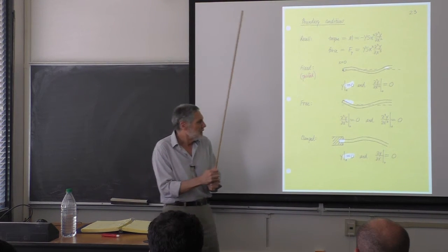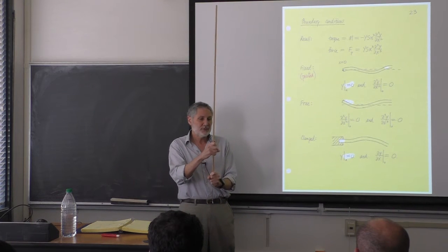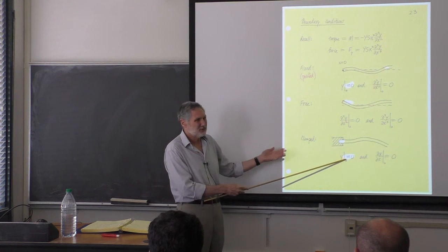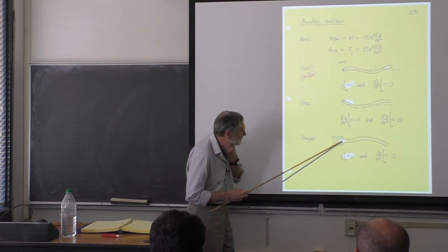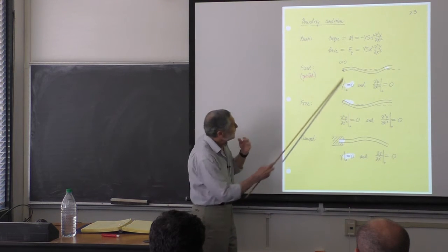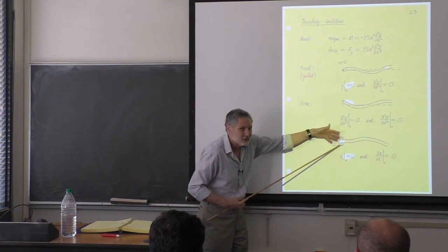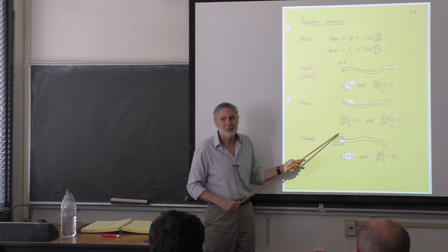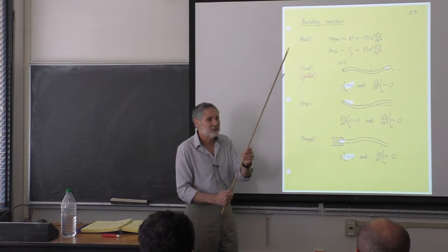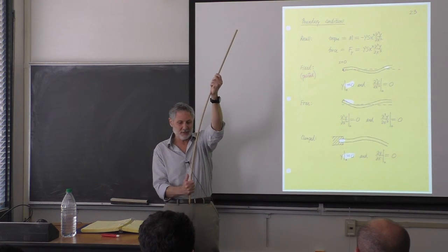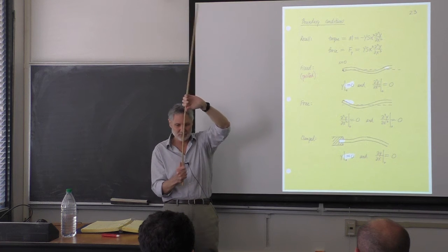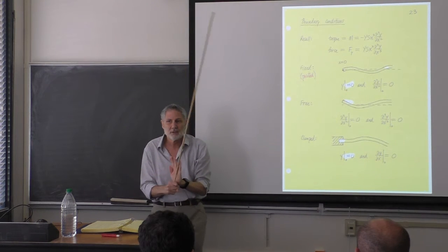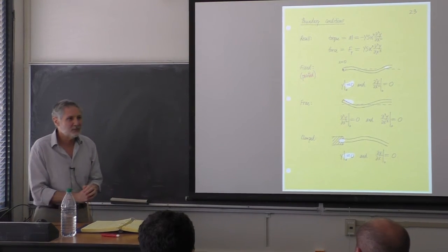Okay? But one of the reasons that person may not have felt much is because you can see what's happening here. For the clamped end, first of all, y is equal to 0, obviously. But what's the next condition? This is not going to help you, because we can have forces and torques, because we got this external influence here. But what does the slope have to be here? Continuous. It's got to be 0. Yeah, the slope has to be 0. So consequently, if something is swaying like this, you can see just from this that it's going to clamp down here. It's going to tend not to sway very much here. The other possibility is that it could have been a node.